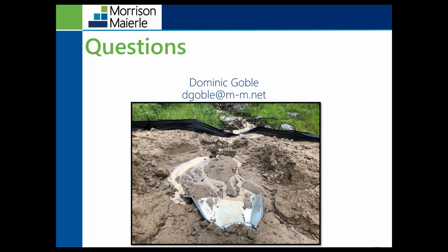But the important thing is to make sure that vegetation, like the grass, has started to grow, controlling the sediment on site. There's no specific time frame for removing the BMPs, but you want to make sure that vegetation has taken hold before removing them. If you remove them before that, there's potential for stormwater or sediment to discharge from your site. So that permit has to be active until the vegetation starts to grow.